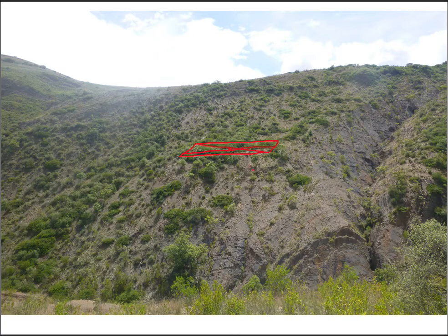And so you'd have to be building wind guys, a huge abutment, all of these things that I discussed earlier that really make it too difficult to build this type of bridge. It doesn't make it feasible for us to build a bridge like this by hand. And so one recommendation I would have is to bring a rangefinder, just a handheld rangefinder with you, because it can be pretty difficult to judge the distance. The difference between 110 meters and 170 meters often is difficult to tell just by eye. And so this is where a rangefinder comes in, incredibly useful, because you can quickly shoot across and say, oh, okay, this is clearly too far away.